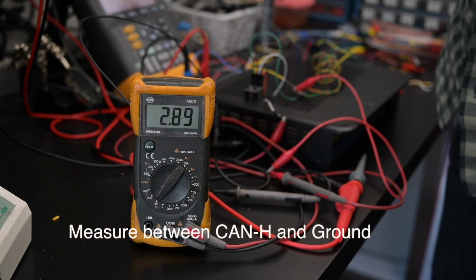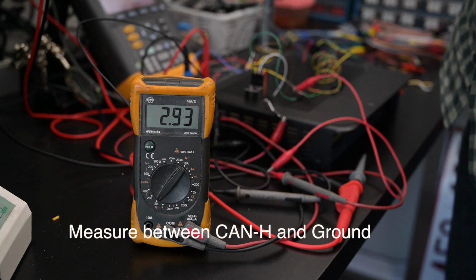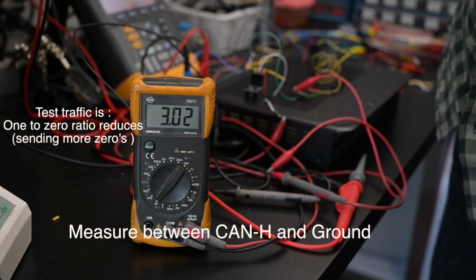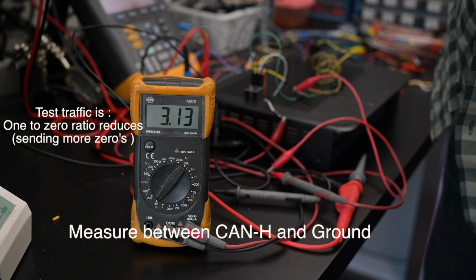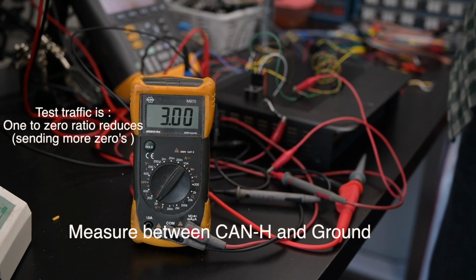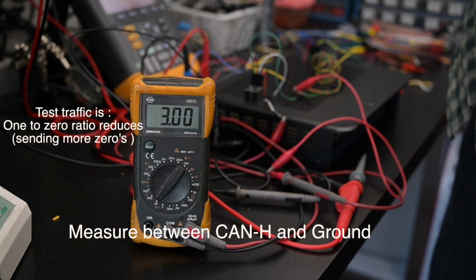Right now we're looking at CAN high, and the signal on the bus is an equal amount of ones and zeros. So if I change that and send far more zeros, that voltage should actually go up. So let's see if this is going to work. And now we're sending more zeros, and you can actually see the voltage is building up. If I'm sending more ones on the bus, the voltage should be going lower, as you can see. So that is a quick test, but then again, I'm controlling the data on the CAN bus right now, and on a live system, that's not going to be the case. You can do exactly the same thing on the CAN low, and you would see the opposite effect.